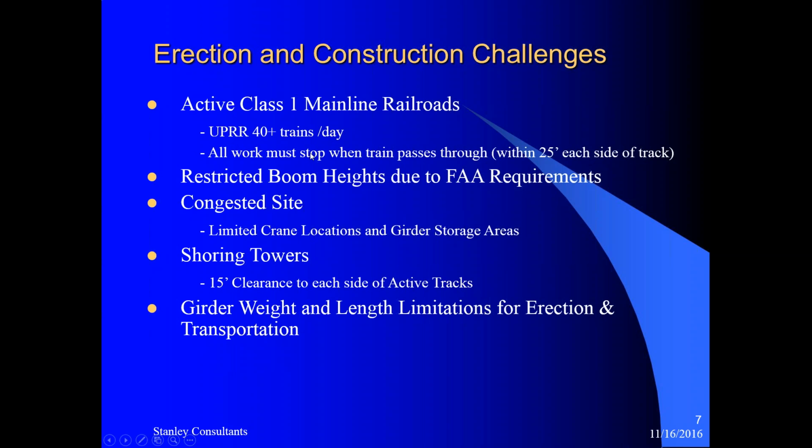Mainly, all work must stop when a train passes through within 25 feet each side of track. This is very significant for erection, transport, and all construction-related work.